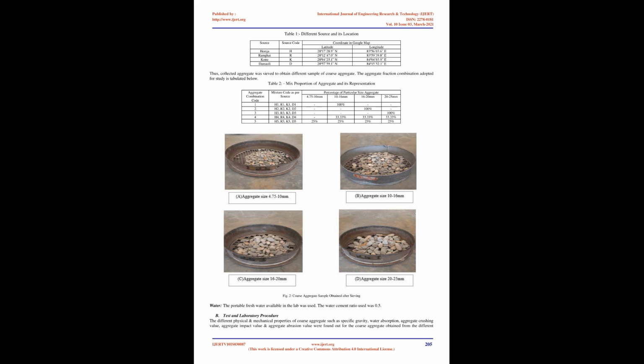The effect of aggregate size 6 mm, 10 mm, 12.5 mm, 20 mm, and 25 mm for 2 nominal mixes, 1:2:4 and 1:3:6, on compressive strength were investigated. The result showed that the compressive strength increases with increasing aggregate size up to 12.5 mm, while the concrete produced using 20 mm had greater strength than those produced using 25 mm aggregate. Moses, Oliphant, and Segun, 2018.